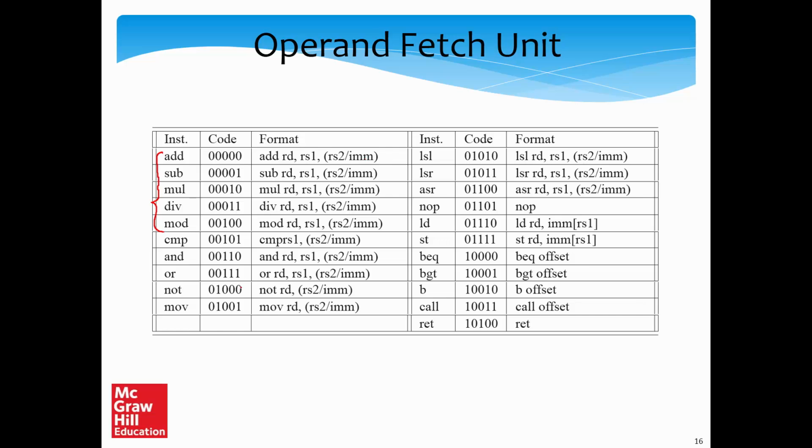The immediate value is actually an 18-bit quantity. The 18 bits are divided into two fields, 16 and 2. So it's a 16-bit constant, and we have space for 2 modifiers plus the default one, so 3 modifiers. That takes 2 bits.